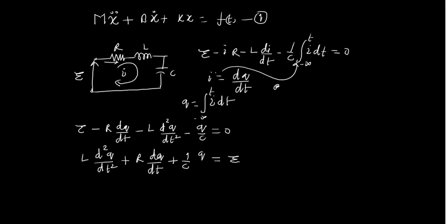Because when we say that we are modeling the system, we write it by writing the differential equations. Differential equation is nothing but what? We have applied the laws by which that system is governed. Here we applied laws of motion, and so we got the first equation. Here we applied Kirchhoff's law, and we got the second equation. So whatever law is governing, you take the help of that and write the equation of dynamics. So this is your second equation.